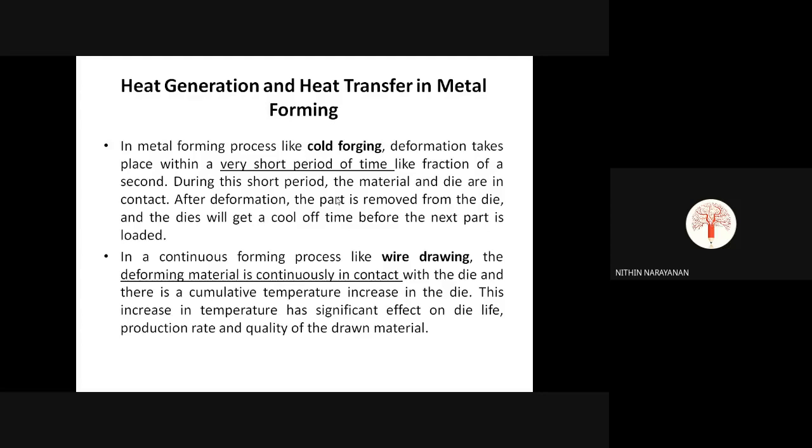But in the case of continuous forming operation like wire drawing, the deforming material is continuously in contact with the die. So what happens? There will be a higher amount of heat transfer to the die or the tool. So it will affect the tool life, or it will affect the further quality of the material drawn using the wire drawing operation. So we are looking only at the problems due to heat transfer, what factors there are, where heat transfer occurs, and what its problems are.